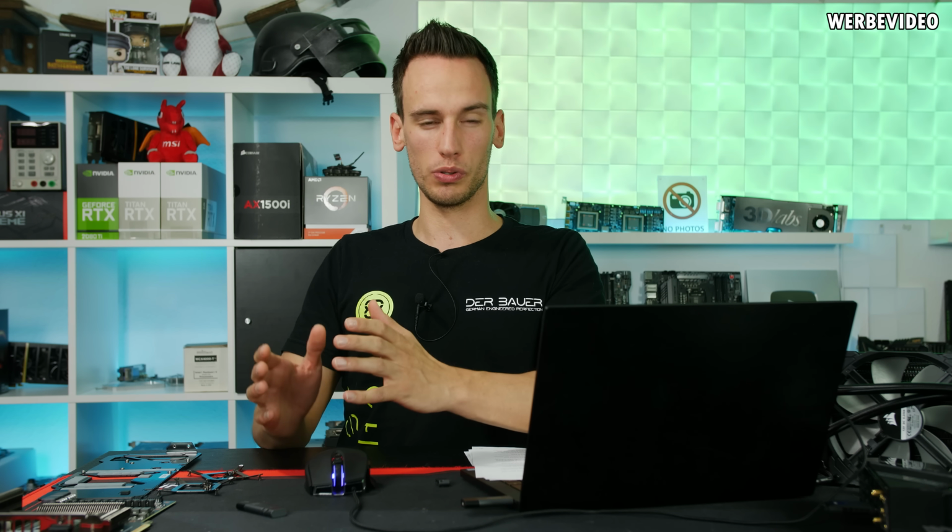That's kind of interesting. I mean, most of you, or I hope at least some of you, were wondering why is a 3700X with 8 cores not twice as fast as a 10700K, for example, which is also 8 core, but it's 14 versus 7. And that is because you just can't, with a single number, compare processes of different factories. That is not how it works. You can compare, for example, 14 nanometer Intel with 10 nanometer Intel. That's something you can do. You can compare 12 nanometer TSMC with 7 nanometer TSMC. That's something that works, but within the different factories, you cannot compare this.